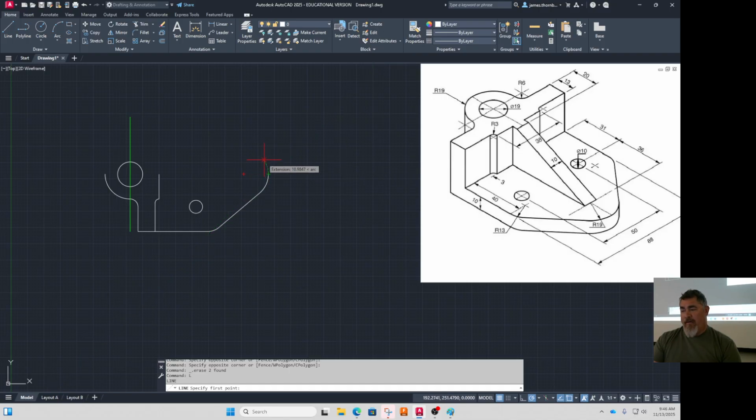But even on an arc now, because I have extension turned on, it'll track using extension around that same diameter of that circle. So that's one you can just play with and see. Just practice, turn it on, turn it off. Find an intersection.